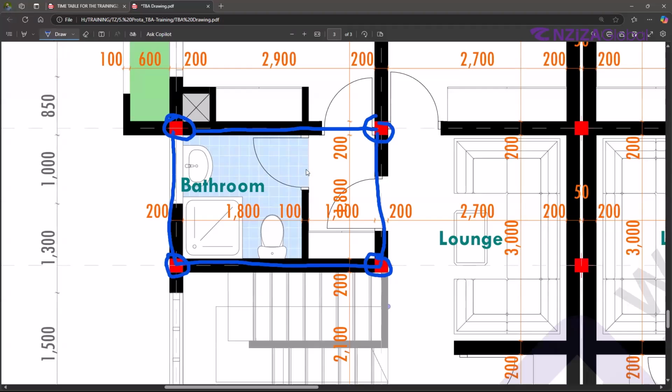So if you apply this load, it will be sitting on a slab. It will be different to someone else who has provided this and also a beam here. For that one, this wall will be sitting on a beam. But if you didn't provide a beam here, then this wall will be sitting on a slab. So that's what you are going to do.